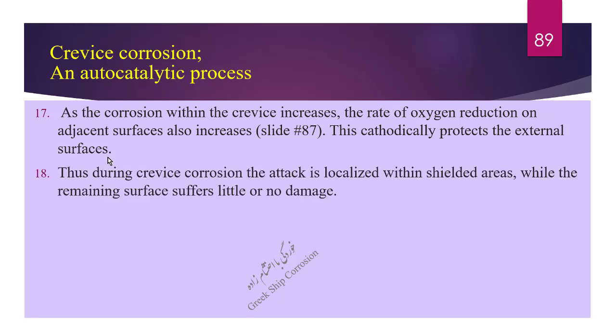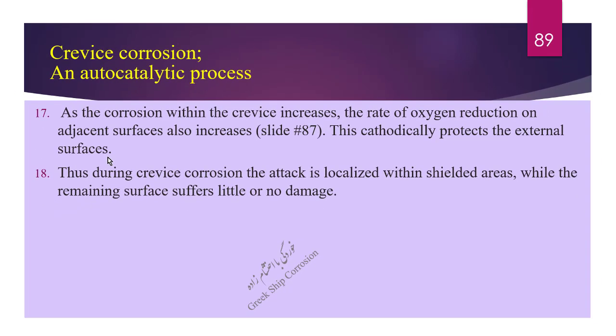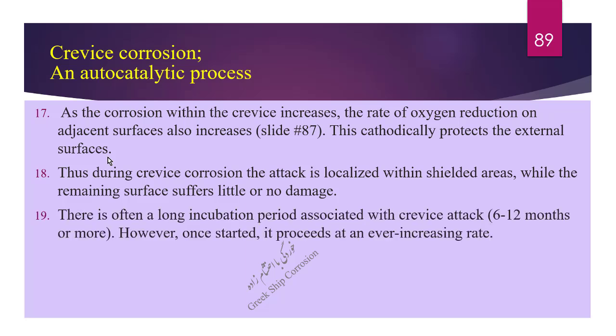18. Thus, during crevice corrosion, the attack is localized within shielded areas, while the remaining surface suffers little or no damage. 19. There is often a long incubation period associated with crevice attack, 6 to 12 months or more. However, once started, it proceeds at an ever-increasing rate.